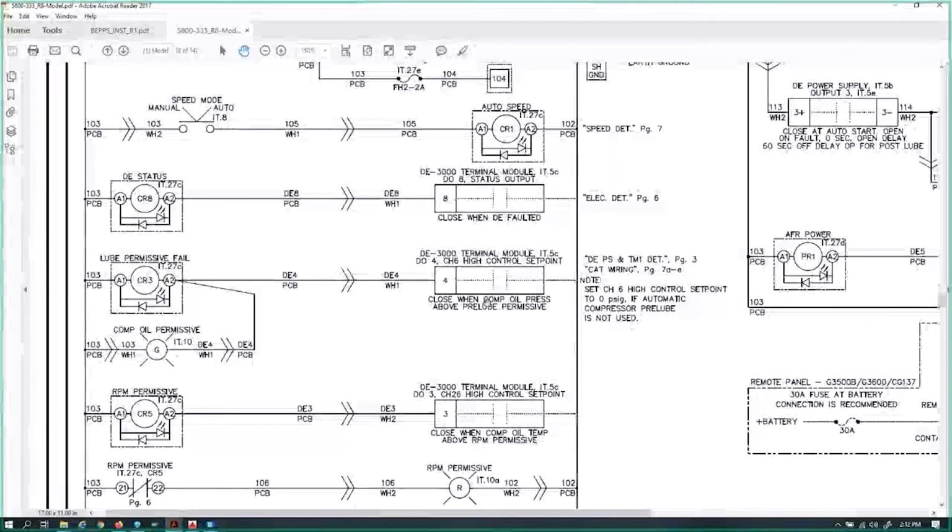So what we just did was we troubleshot a schematic, but we never had a problem in the schematic. What we had was an operator that thought he was actually changing a high safety shutdown point, which happens on a quite regular basis. But instead of changing the high safety kill, they changed the control set point. And it happens quite regularly. So that's one example. Now, maybe everything right there was programmed right, but his answer was, well, it never prelubed.